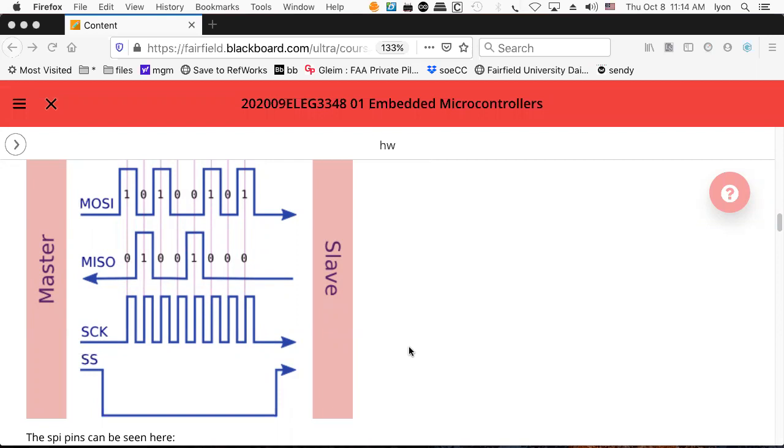And so that's nice. The basic limit, of course, is that you've got to select every single device. So your master will always be the CPU and the slave will always be some device, and you can't go faster than the device can take. So that's a basic fundamental limit. That's the serial clock input for your device. And you can find out what the limits are.